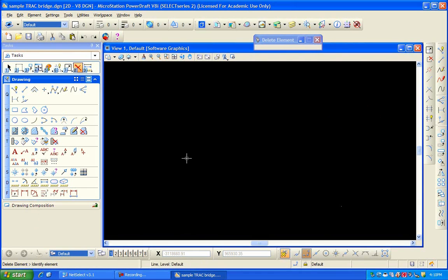Now, one tip I'd like to mention here, especially when you're deleting, is that when you're done using the tool, it's good to do a reset button with your mouse, which in my case is a right click. Sometimes I even like to come in and do an element selection because that won't hurt any elements I've drawn. That way I know I will not keep the delete button pushed in and delete other things later down the road that I don't want to.